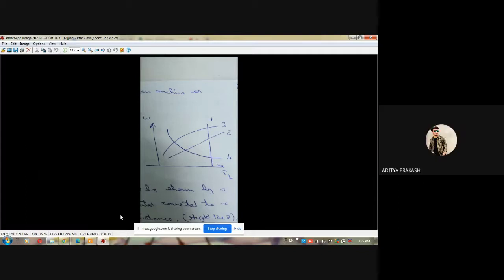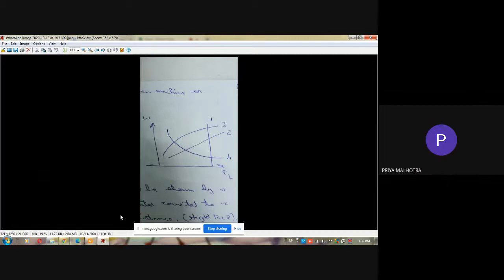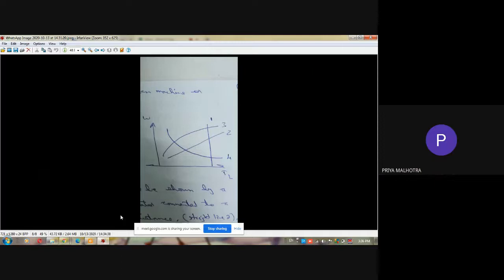Now tell me, if torque is inversely proportional to the speed, what happens to the power? Constant power, sir. Yes, the power remains constant. Power is proportional to the product of torque and speed. So in the characteristic given by curve 4, as the speed is increasing, the torque is decreasing, or as the speed is decreasing, the torque is increasing, so the power remains constant. Characteristics of this type are exhibited by certain lathe machines, boring machines, etc.